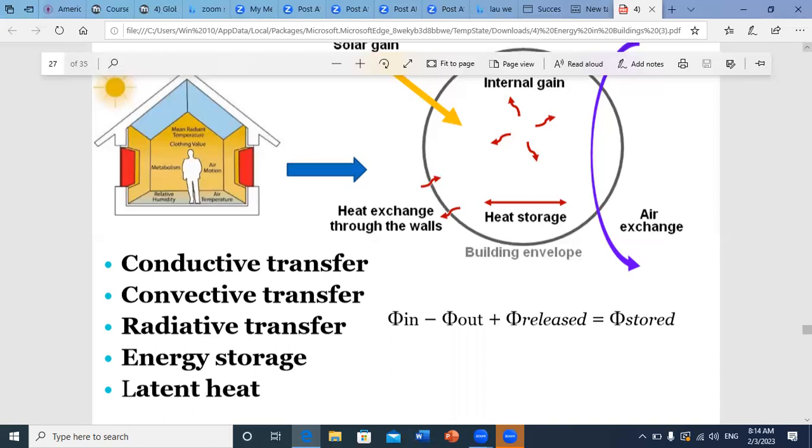because you know that in this zone we have very large temperature difference between day and night, and therefore implementing such systems in the building will reduce a lot the fluctuations of temperature inside the building, because in the day you have a lot of sun, you will have penetration of heat fluxes towards your room, which will lead to heating of air. In case you don't have, for example, materials that can store this heat, this will lead to overheating of air inside your room.